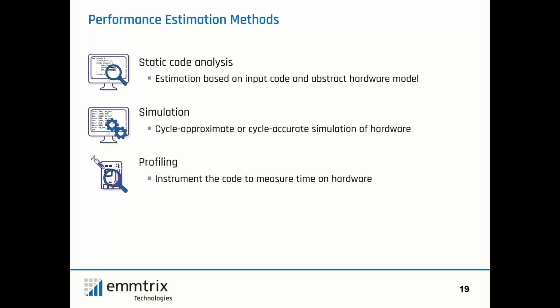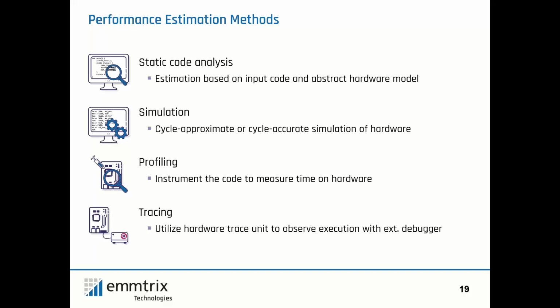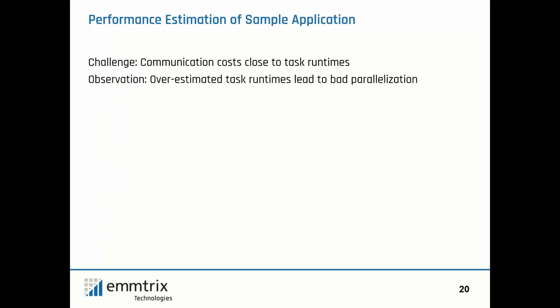Then there's also profiling. There you run the code on the hardware and inject code into the program that measures the time on hardware. Then there's hardware tracing. You use an external debugger and the hardware trace unit to observe the execution closely on the hardware, which is the most accurate method.